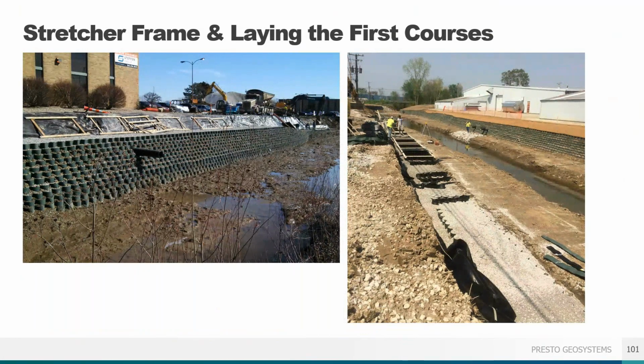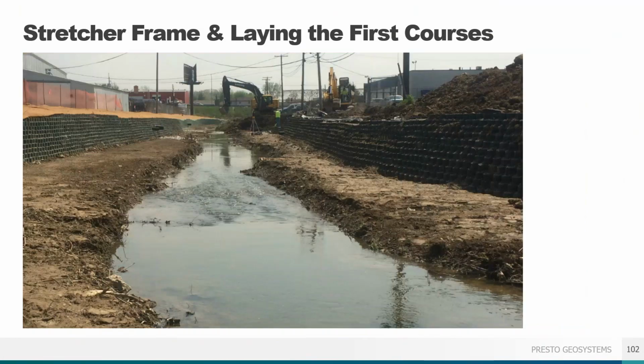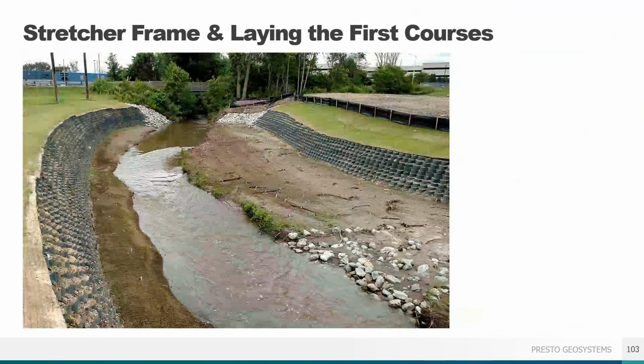And as one side of the stack channel was completed, on to the other, also using stretcher frames. And here we see the newly constructed GeoWeb walls on either side of the watercourse. And as vegetation begins, the front fascia cells were seeded with a native plant mixture and an aggregate topsoil mix. Notice the slight curve on the wall towards the top of the screen.